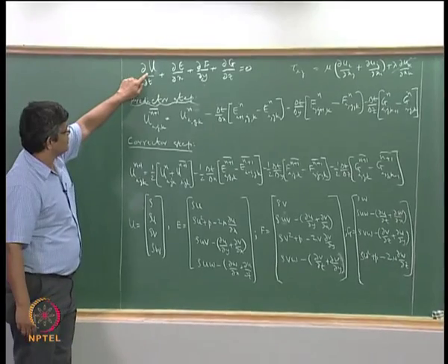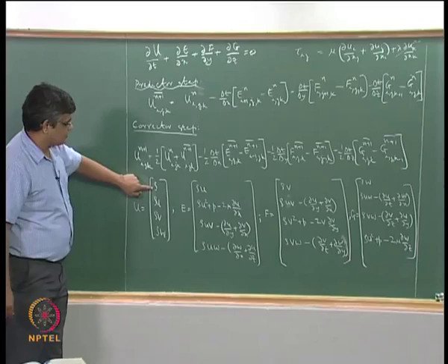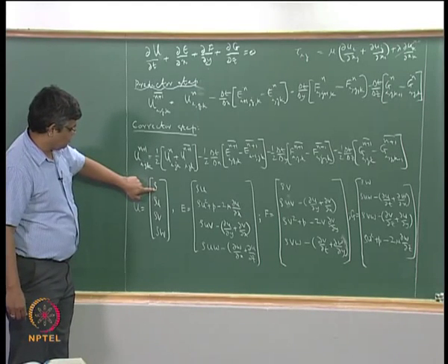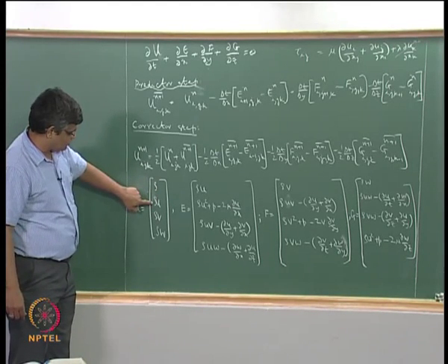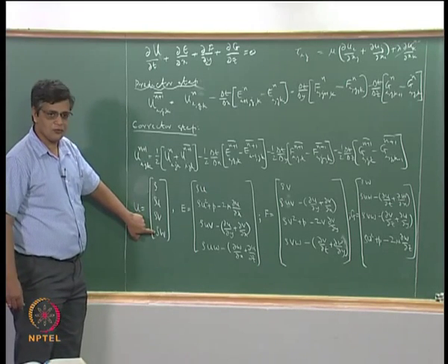and under those conditions we can write down the components of u, which is the main variable of interest: in the continuity equation we have rho, in the x momentum equation you have rho u, y momentum equation we have rho v, z momentum equation we have rho w.